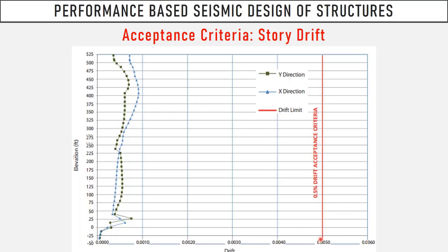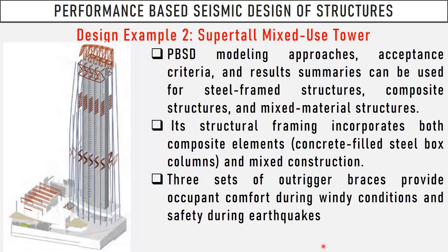quite an achievable limit. It's not that low, because we are all accustomed to 1% to even 2% limits in classical reinforced concrete mid-rise buildings. But once you go to high-rise buildings, you control the lateral displacement, and 0.5% is not that low. In some cases, you need to control the deformation with different innovative techniques, like so-called